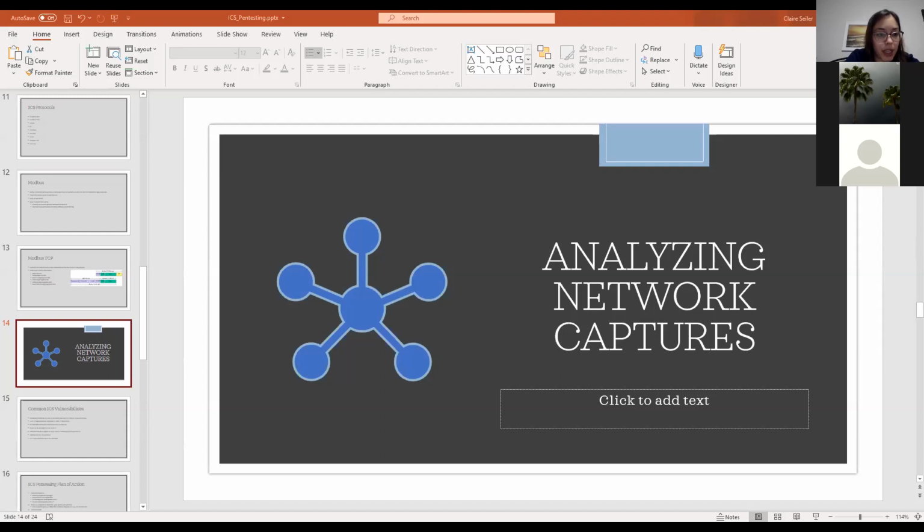The PLC responds back and says what the value of that coil bit is. So I think it was just requesting the first coil. And then this one, it looks like it's requesting the second one, and then it responds with 0, so that coil is 0.